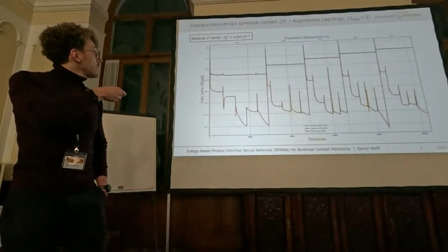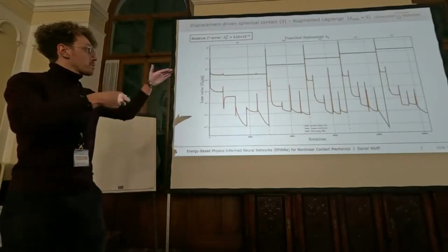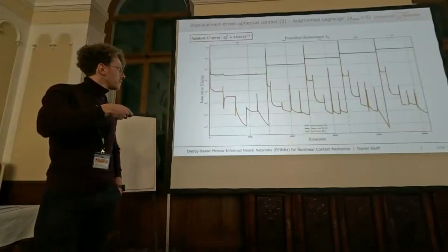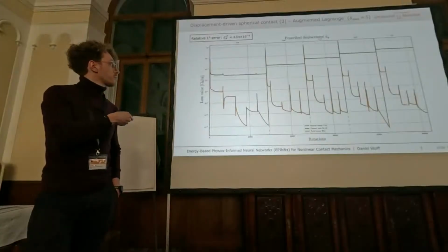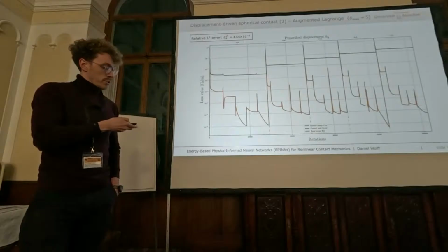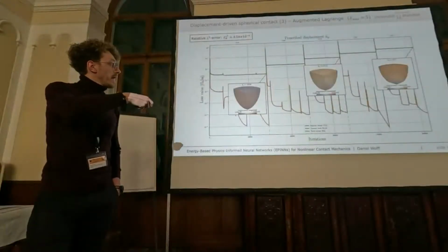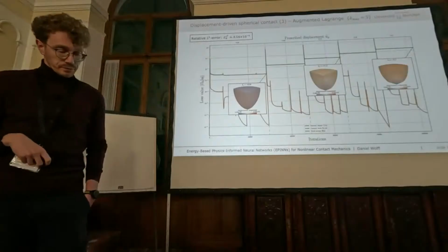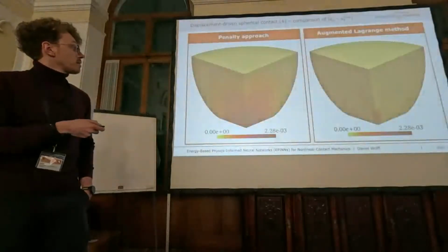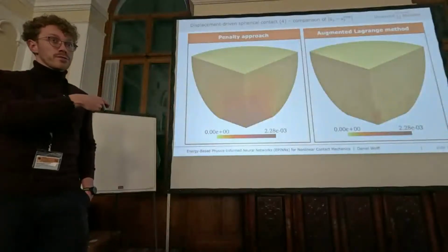Now what we see is that we again have these steps for the total energy, but now we get these additional plateaus here for the additional Uzawa iterations that we have in each load step. And we get a much lower error, at least by 1 order of magnitude lower. And again, we also get the progression along the nonlinear load path. And we can look at the actual error compared to the FEM reference solution.